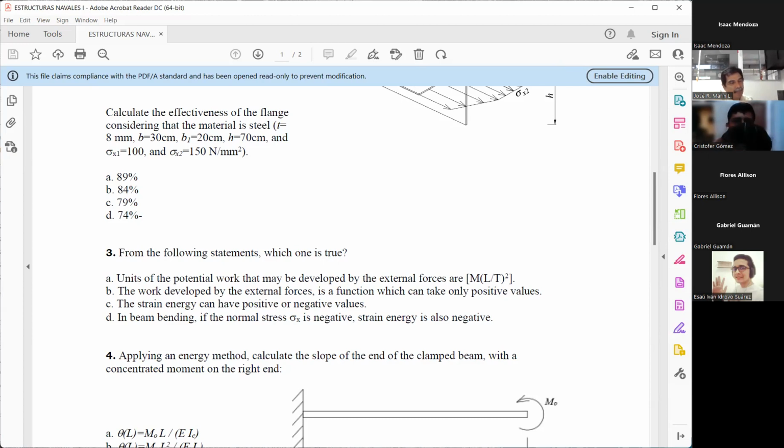Okay? And remember, when you calculated it for a beam, you said it's equal to what? The moment squared. When you square something, you automatically get positive values, right? If you divide it by E I sub C, E is always positive.